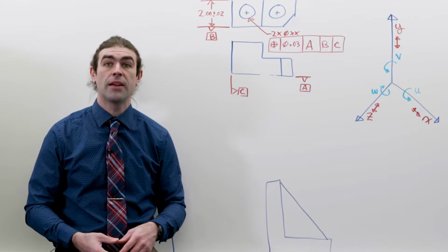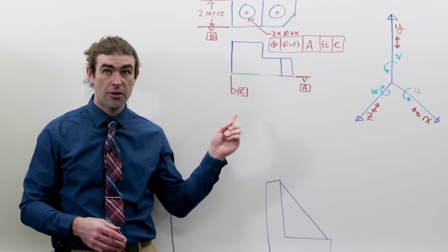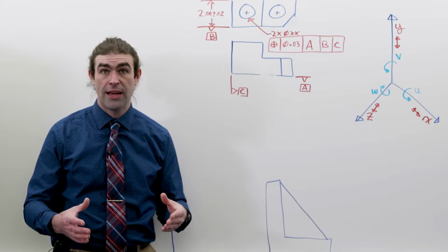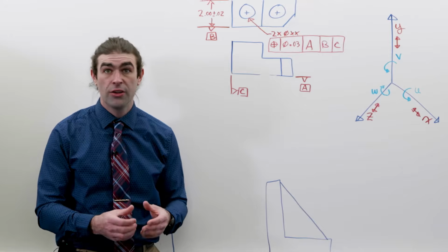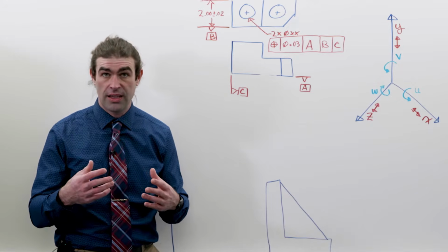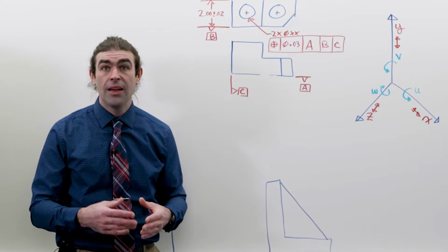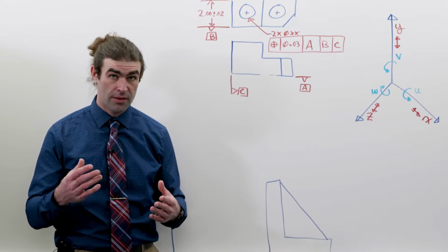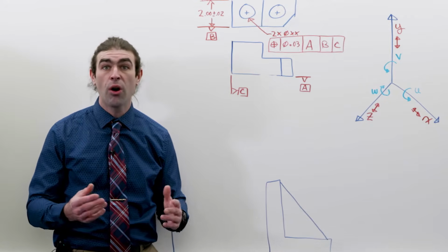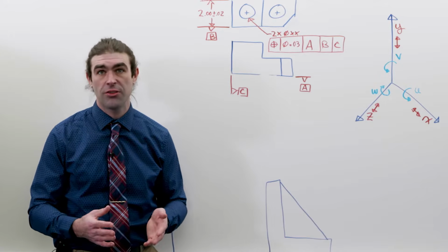So a surface plate for a regular surface datum, or a mandrel if you have an internal datum, so an internal hole. You could use a mandrel to expand and capture that. Gauge pins also work. The largest gauge pin is the feature simulator for a lot of holes up to about 1 inch.